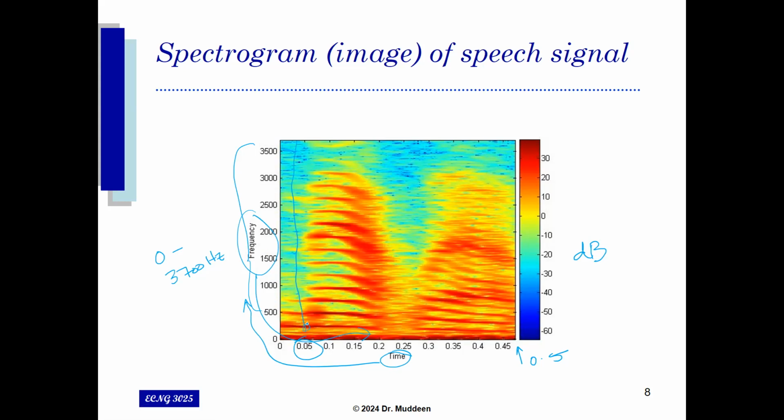There's a heavy frequency component here at 500 hertz, and let's say about 750, and then nothing else pretty much happens. So you can sort of manually figure it in your mind. If I were to draw this out as frequency and amplitude, at that particular point in time, it looks like we have a spike at about 250, another one at about 500, and then a slightly lesser one at about 750. So that's what the spectrum at that particular instant in time looks like.